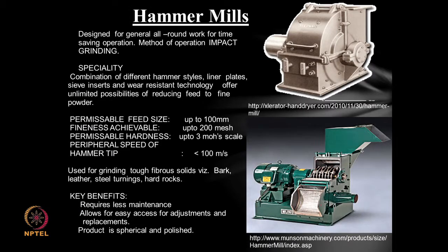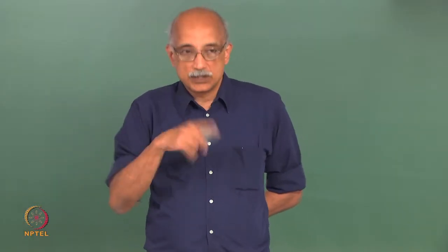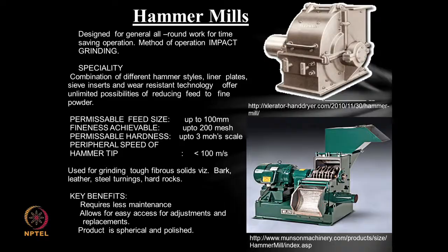So, what are some types of mills? Hammer mills are used to reduce particle size from a crusher. Essentially the way this works is you have hammers that are actually mounted inside a chamber, and as the particle flows through, they are subjected to repeated impacts from these hammers that are typically attached to a rotary machinery within the chamber. So, a hammer mill works by the principle of direct contact between the hammer surface and the particle whose size you are trying to reduce.